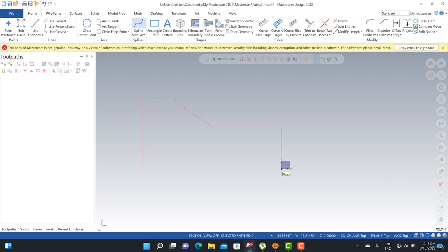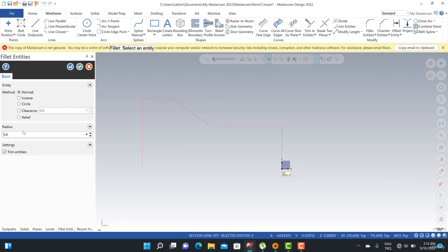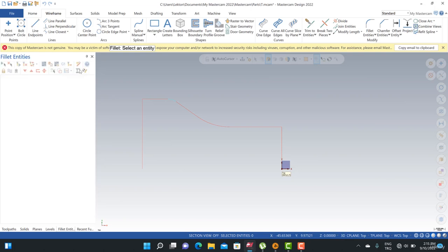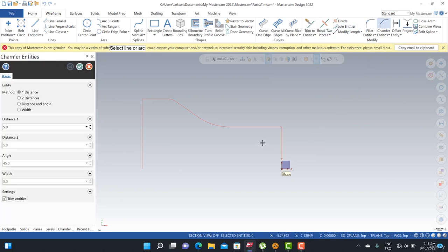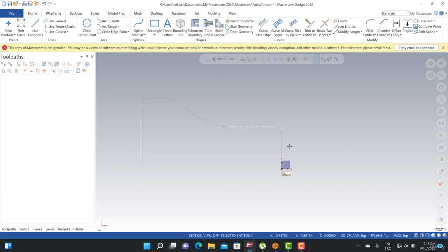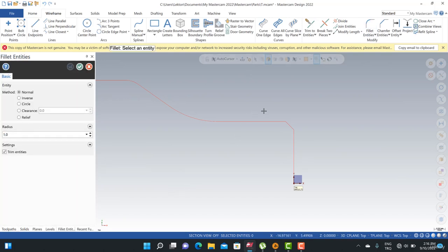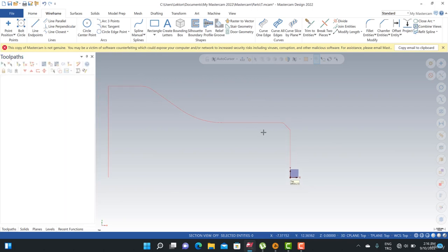And after that, of course, we can turn to wireframe and some fillet here. I'm just going to create a 20 millimeter fillet here, and then I'm going to hit the blue OK button, and then maybe we should also create another fillet here, and it can be 5 millimeters, and then maybe we should create some chamfer here. It can be 2 millimeters. Okay, and maybe we should also create a little fillet here. It can be 1.